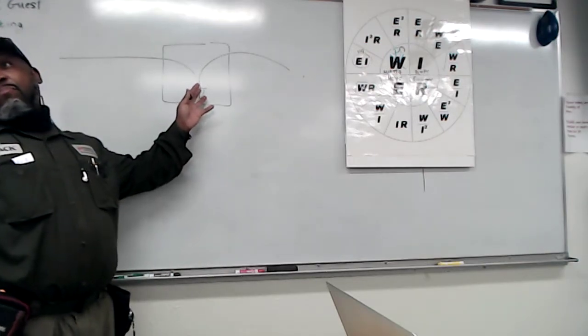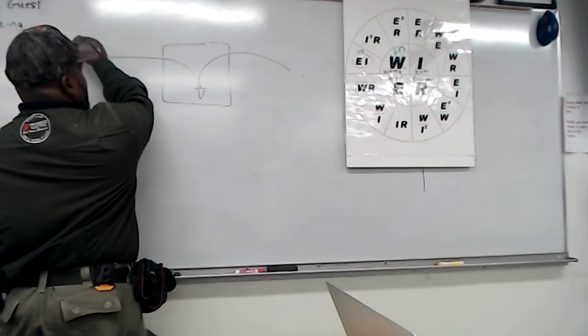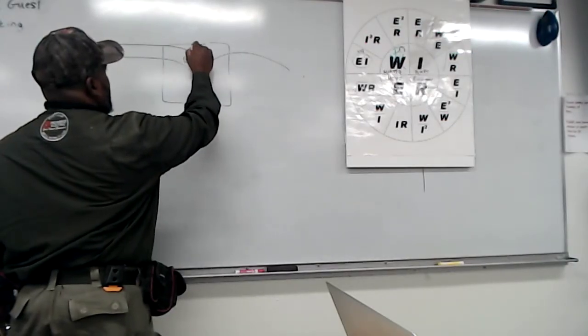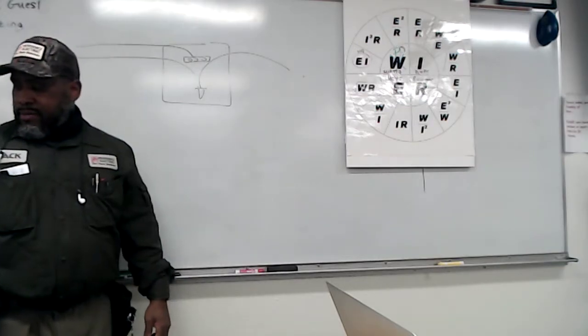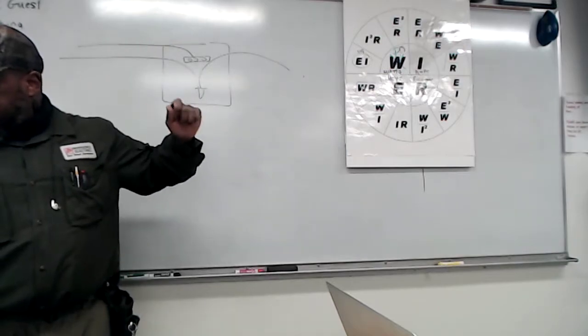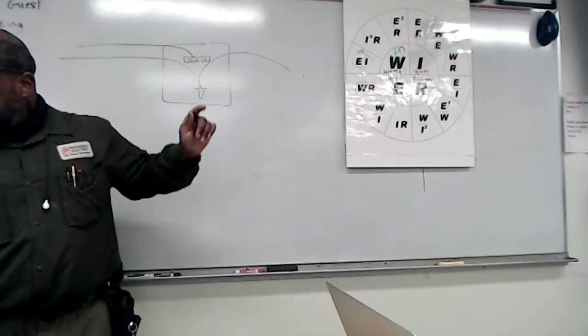Oh, actually, that's spliced. Sorry, if it terminates, how would it terminate? I guess on a terminal block or something. If it terminates, it gets counted 1 time. Each conductor that originates outside the box and terminates or is spliced within the box should be counted 1 time.